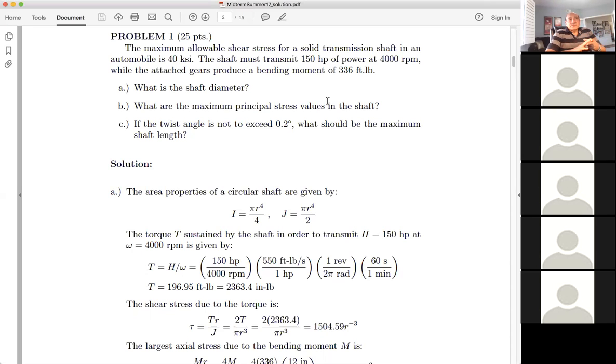From that, we should be able to determine the torque for sure, and the torque means some force, right? So you have something on the shaft, and usually the topic for design of the shaft is the selection of the diameter of the shaft, as you will see in this extensive design project. Now, the additional little twist in there: if it were just a straightforward calculation where we have the torque, we can calculate the diameter of the shaft given a maximum allowable shear stress. So the calculation would have proceeded like this.